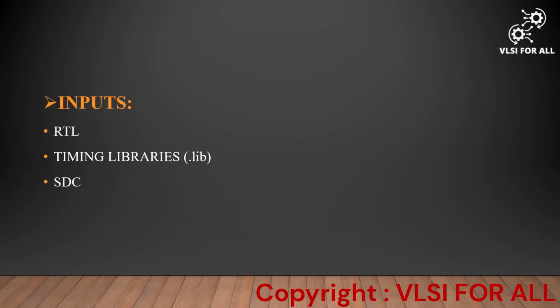First of all, we have to take the inputs. In logic synthesis, we give these three as the major inputs. One is the RTL file, which is nothing but the Verilog file, which comes from the front-end team. The next is the timing library, which will be given by the vendor. And the SDC file, the constraints file, will be provided by the constraints team.